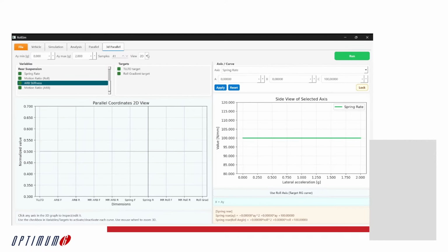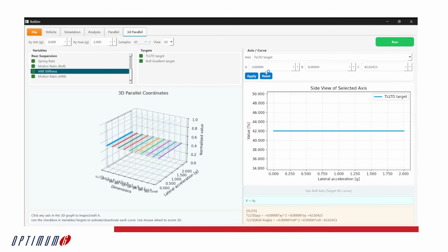Say that we're gonna set an LLTD target. You do not want an LLTD that's constant, but one that varies with the lateral acceleration. Something we can take as an example: Felipe talked to us and showed us that in the skid pad optimization, the LLTD would vary with the roll angle, or in that case, the turn radius.